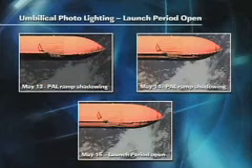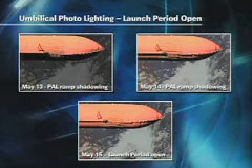What we did is we simulated in the computer, for different launch times, what that lighting would result in on the tank and what you could see. Our launch date, if you remember, is May 15th. Two days before it, on May 13th, we did the analysis. We handed this picture over to the external tank project, and they looked at it against their requirements and said, no, the protuberance air load ramp, the amount of foam that forms a ramp by the cable tray, you can't see it. That's an area we would really like to verify has no shedding from it. So May 13th was thrown out as a possible launch date.